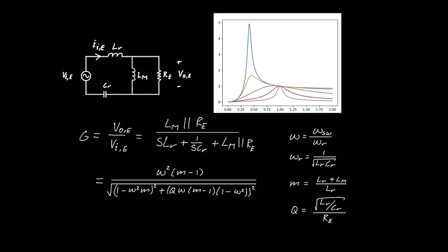So usually one designs the LLC such that, for example, the yellow one is the worst case, the case where you have the highest load. So if you then increase the switching frequency, you will get a lower gain. And if you decrease the switching frequency, you will get a higher gain. However, if you have too much load, you will get a lower gain when you also decrease the switching frequency. So it's important that you design it well such that the worst case also increases.